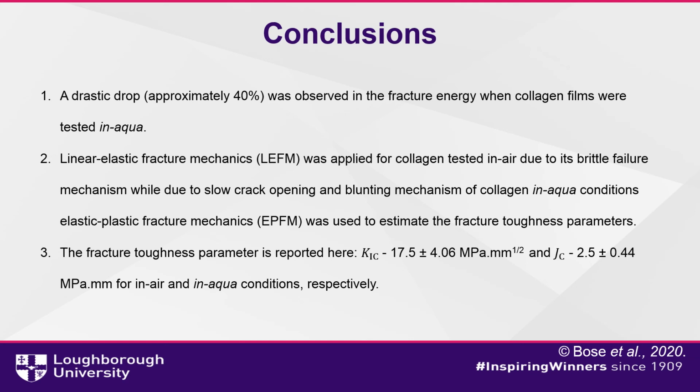Second, analysis of deformation behavior in air and in aqua conditions confirmed that linear elastic fracture mechanics (LEFM) may be applied for collagen tested in air due to its brittle failure mechanism, while due to slow crack opening and blunting mechanism of collagen tested in aqua conditions, elastic-plastic fracture mechanics can be used to estimate the fracture toughness parameters.